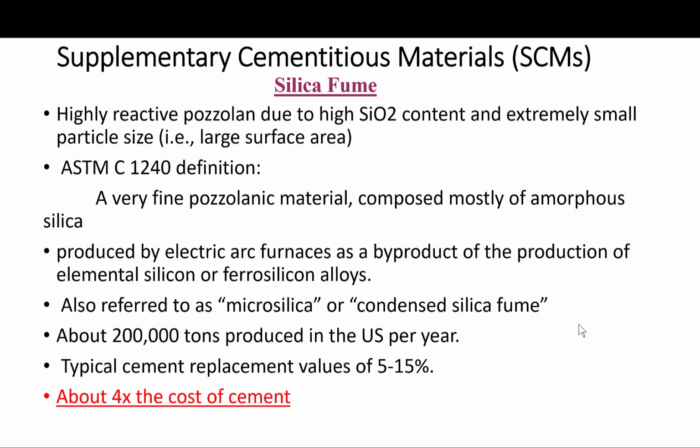The typical cement replacement values are between 5 to 15%. It's very expensive, estimated at about 4 times the cost of cement, so its use is not really economical. It's purely technical and probably has some environmental benefit, but it's not economical in this case.